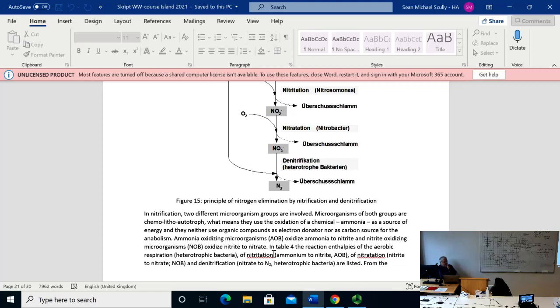And then the two ladies from Hannover University, for Bayer, and there was someone else. But they both said, yes, there is a certain production, but if you relate it to the load of nitrogen being eliminated, it's more or less the same ratio which you have in a treatment plant. In a treatment plant we talk about concentrations of maybe less than 100 milligrams per liter, and here we talk about concentrations of 2,000 milligrams per liter, and in that relation you have a factor of maybe 10, 15 more N2O formed.